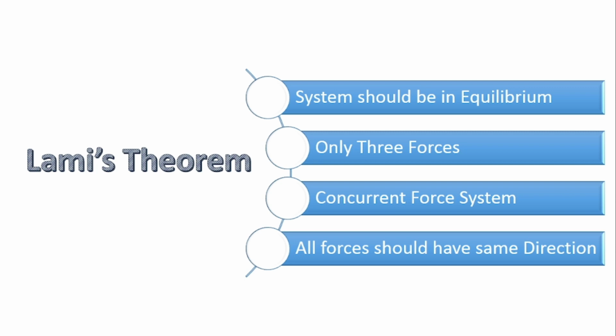At the end, all the forces should have the same direction. All the forces should be pointed either in the outward direction or in the inward direction. If it has a combination of outward and inward forces, then we cannot apply Lami's theorem.